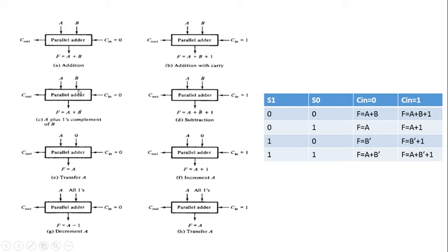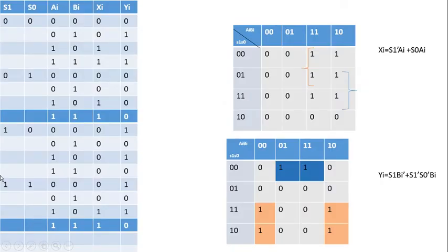Complement of b is kept as the yi input of this parallel adder in both this case. Okay, so make this combination for 1 1, with all 4 possibilities of ai and bi. a is kept as a itself. So 0 0 1 1, here for xi also 0 0 1 1, and yi is kept as the complemented form of bi.